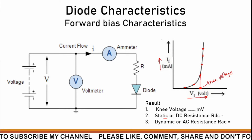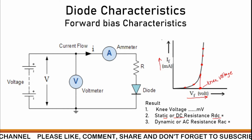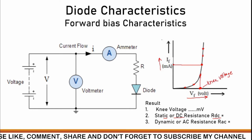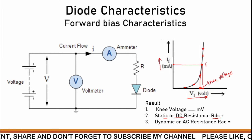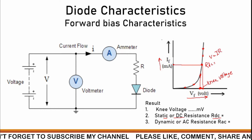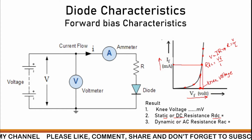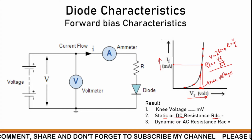Now, how is the static or DC resistance RDC calculated? Just take one point, make that point intersect the y-axis, and again make that point intersect the x-axis. So RDC, according to Ohm's law, V is equal to IR. So if you have to calculate R, R should be equal to V divided by I. V means Vf at that point, and I means If at that point, which will give us the static or DC resistance at that point. This is the way to calculate DC resistance, or static resistance.